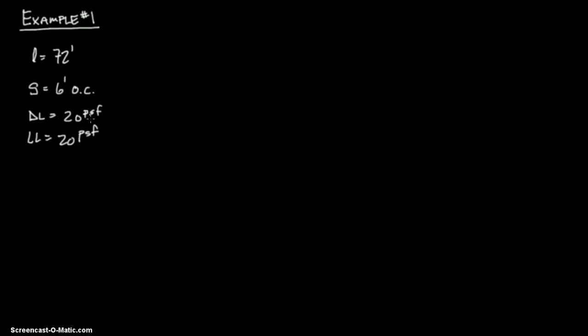Then the dead load is 20 pounds per square foot, 20 psf, and the live load is 20 pounds per square foot. And the live load deflection is limited to, let me say, delta max, this is deflection max, equals L over 360.